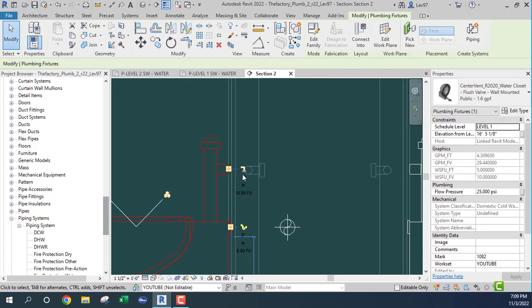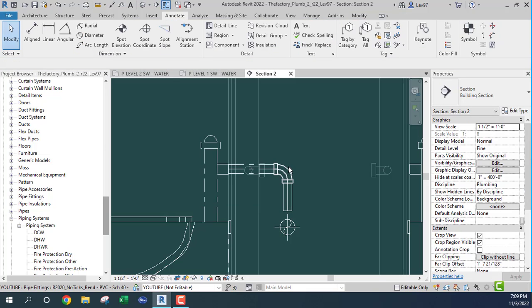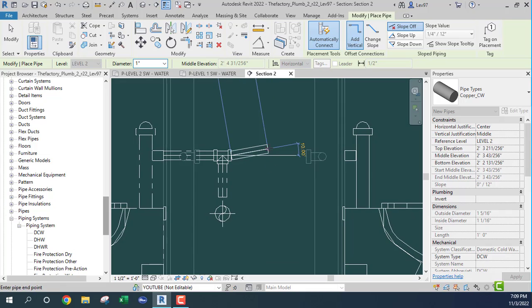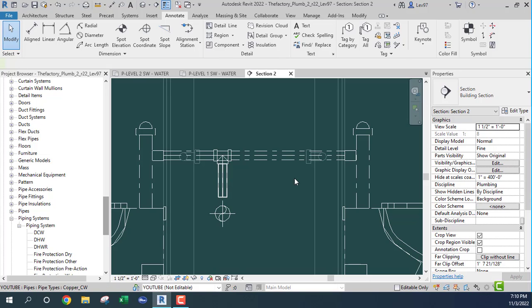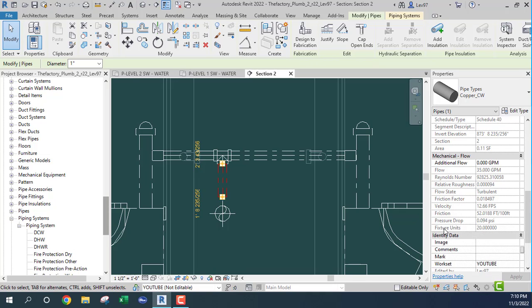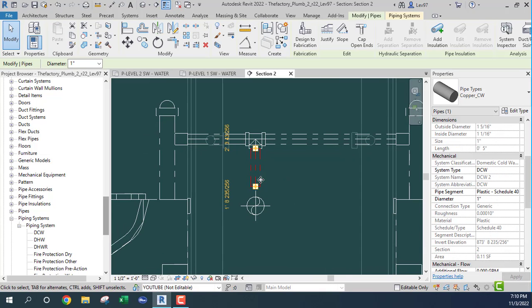Looks like we're going to be going down into, so go here and get our construction design line, I should say. Go here. Now this is easy like Sunday morning. Go over and we connect into, and we should get fixture units. What's that, 20? 10 each? Where is it? Yeah, okay. So we got 10 each fixture units. That's 10. Okay, they're reading it here. And flow is 27.